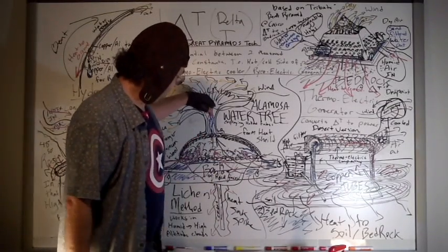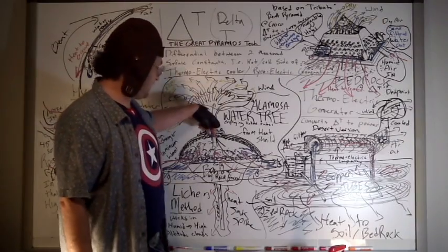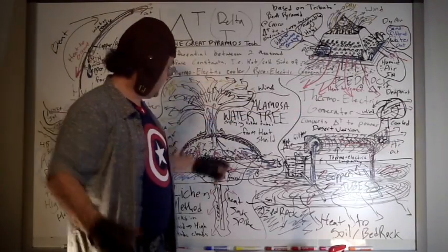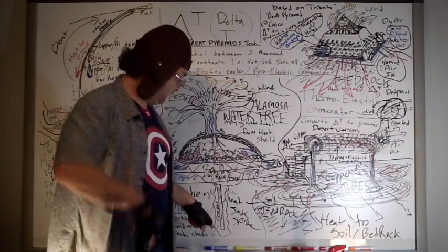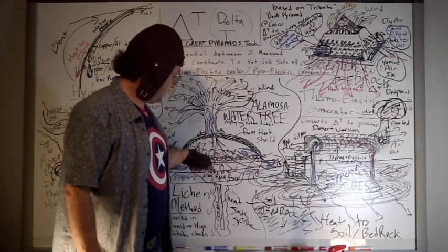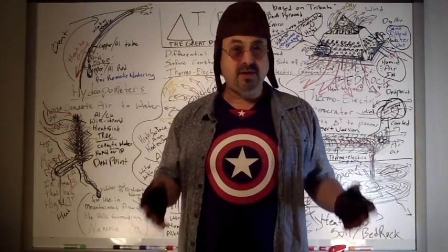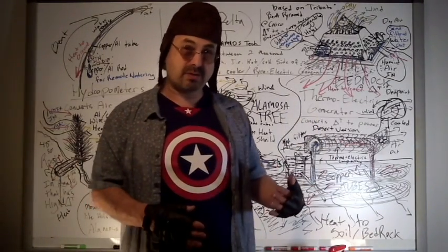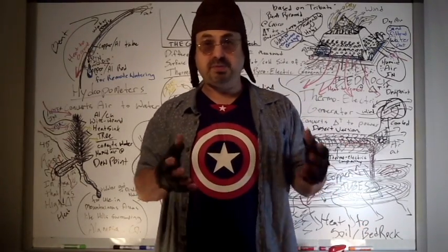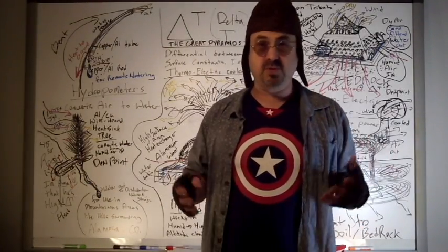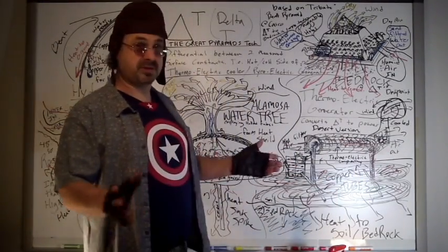Now in this particular drawing here, you see I put a heat sink spike. This would be like if you take a great big boulder sitting in a garden, you drill a big hole or multiple holes through it and put heat sinks down as far as you can go so you can get that heat down there. And that heat sink spike's probably going to be made out of aluminum. Although aluminum corrodes in the ground, you might want to coat it with something. You can plate aluminum with other metals that'll be more resistant to being in the ground, like copper, for example. Copper doesn't last forever either, about 30 years.